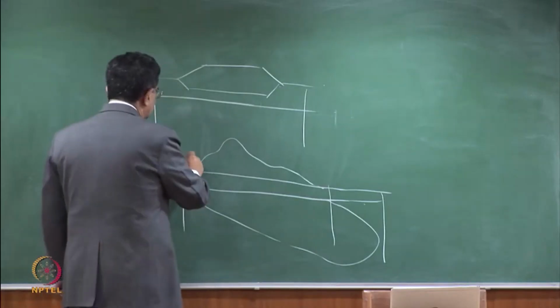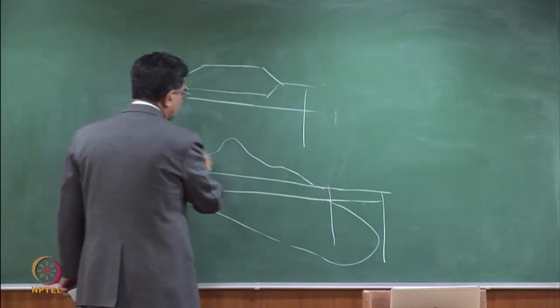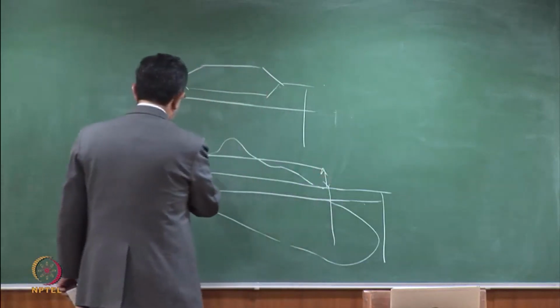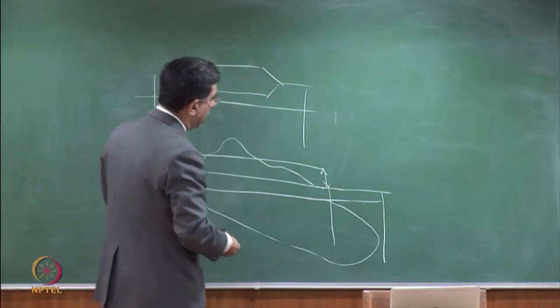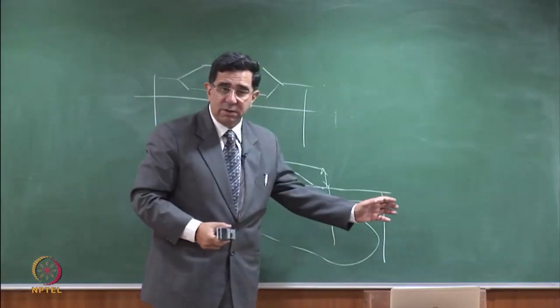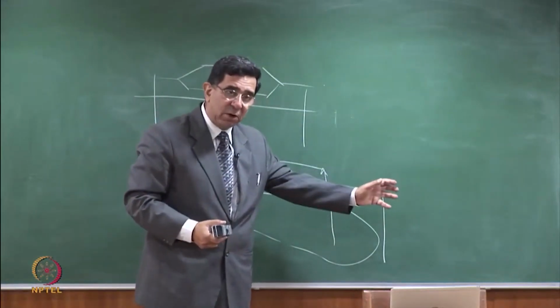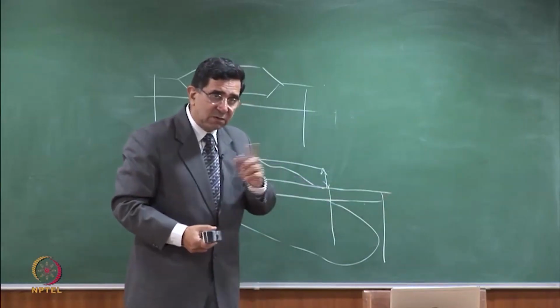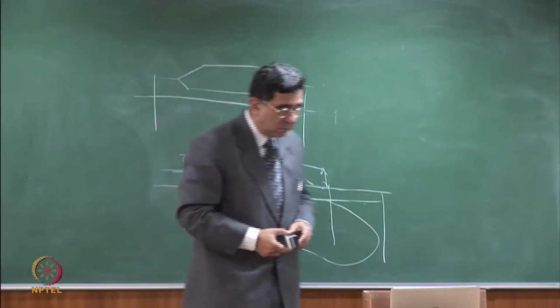So remember, this may be your landfill boundary on the ground surface. But your plume may have crossed your boundary. So you will need to set up the monitoring points outside the boundary of your landfill. That's the difference between an old facility and a new facility.